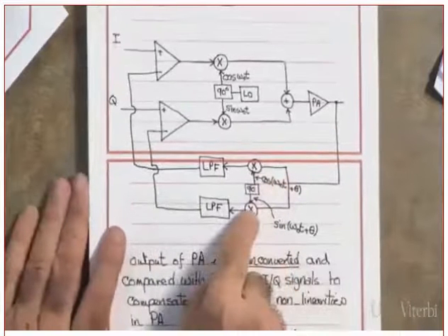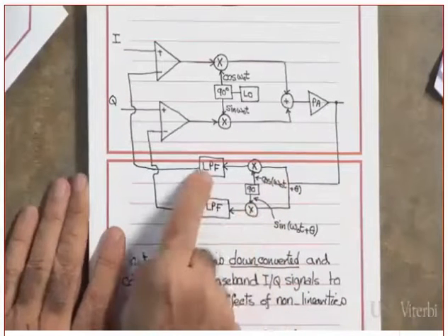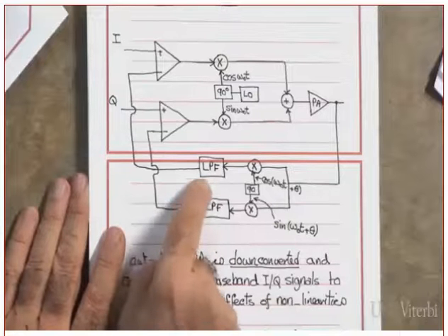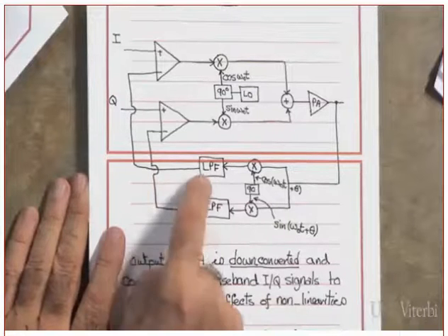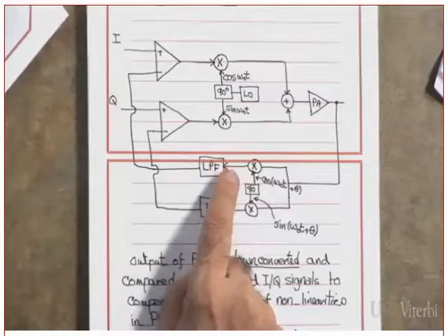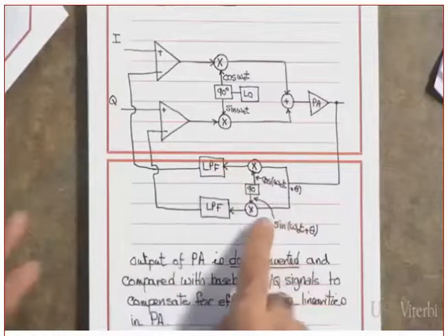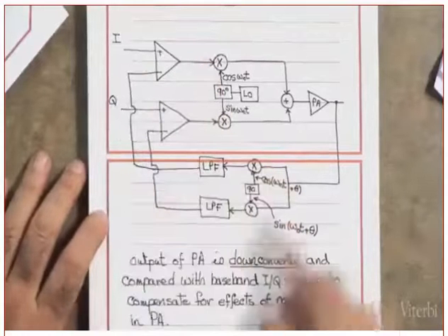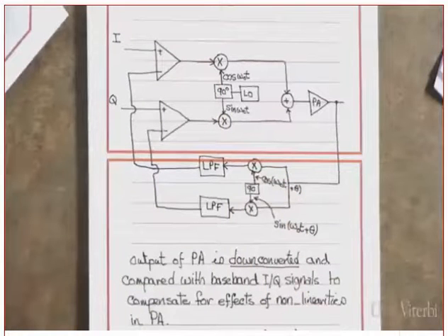So I demodulated, yes? And then I filtered it out. Yes or no? Okay, by the way, I'm assuming the I and Q were already waveform shaped. This one is the same thing, and you compare it with the input and compensate for the difference between them.